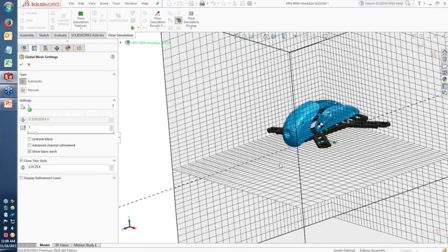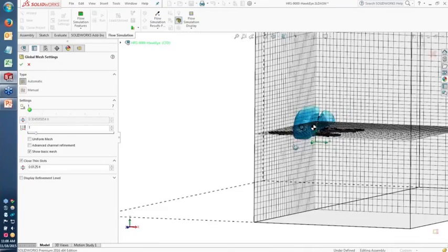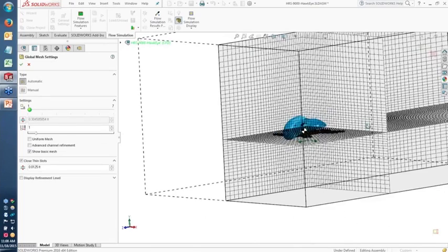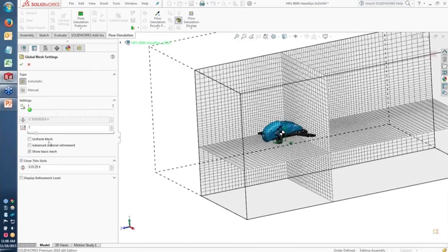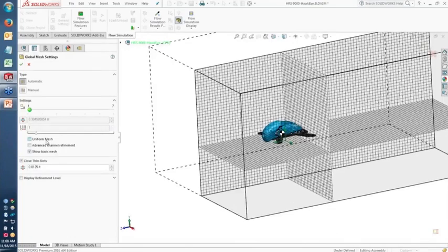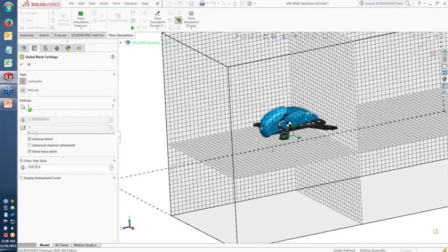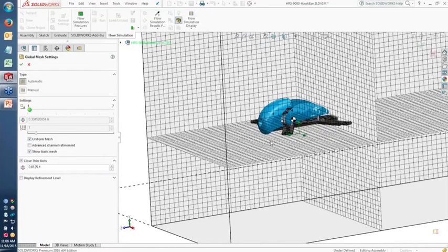But if there are cases where you don't want those cells to just automatically adjust or stretch their size like this, which again the mesher has always done by default, you can override that if you like, and there's a new checkbox called uniform mesh, which will ensure that every cell is the same exact size of the starting grid. Now again, this does not include any refinements that might happen where the cells start to get split up to match the real geometry, which is the next step of the mesh. This is just talking about the starting grid, so to speak.